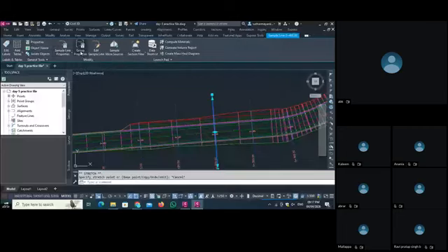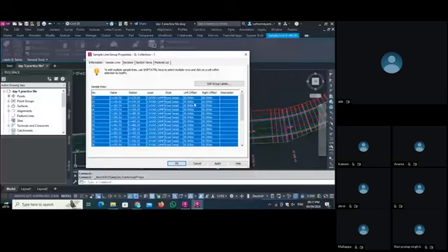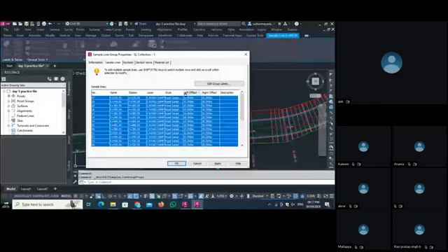If I click the group property, you can see all the sample lines are selected, and what chainage is there. If I select here, press the shift button and select the last one, and then if you want an increment of 10 and press enter, the left offset as I apply, see, it will go at a 10 meter increment instead of 20.